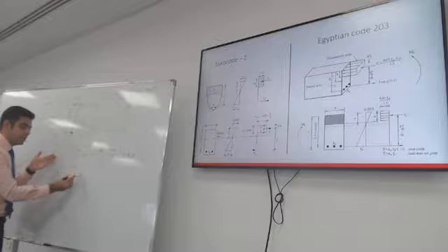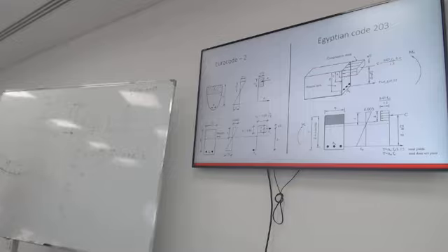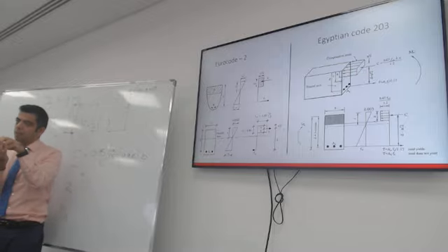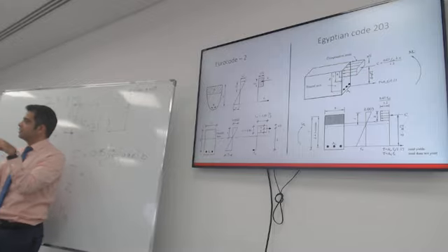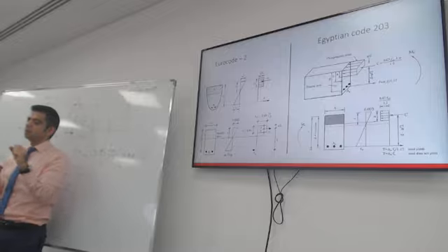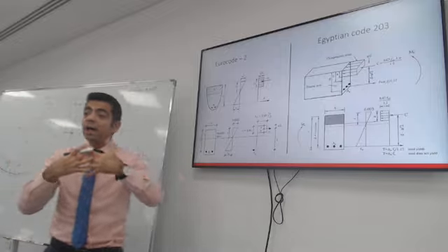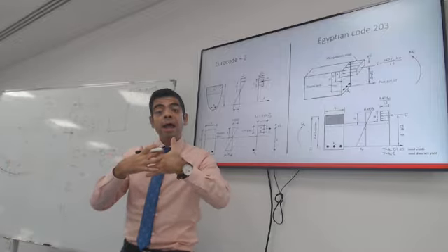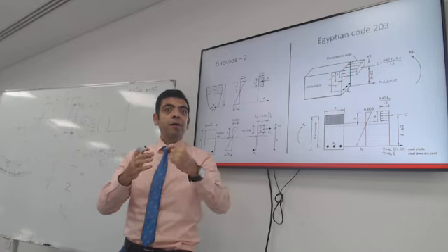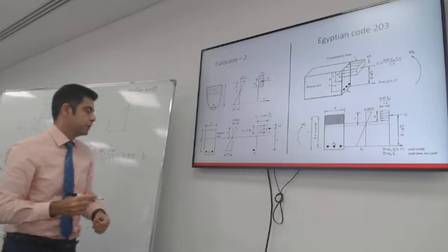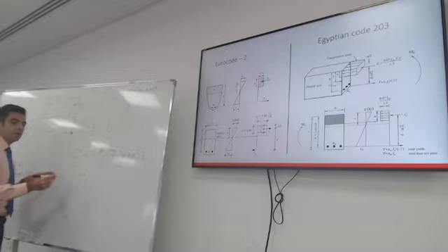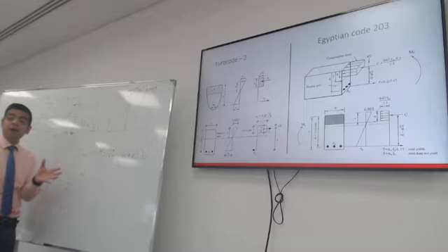What is the tension in the steel? What is the tension force in the steel? It's the area of steel multiplied by the stresses in the steel. Since our design is based on ductile failure, with yield developing in steel first, we assume that the tension in the rebar has already reached yield.